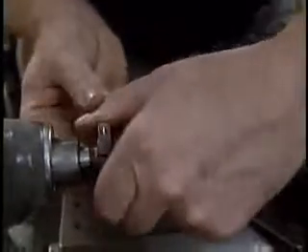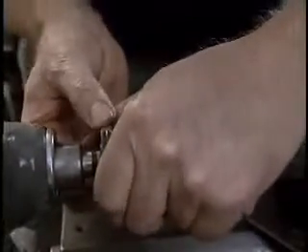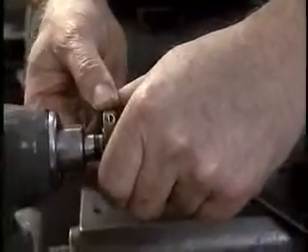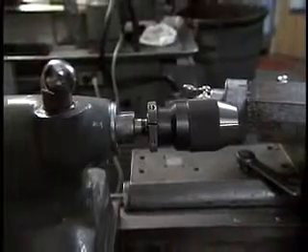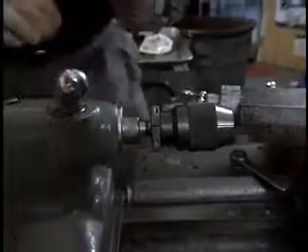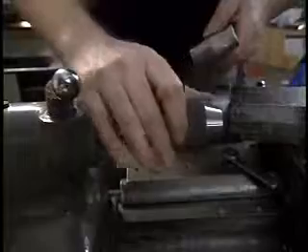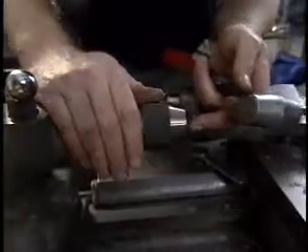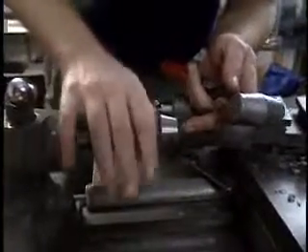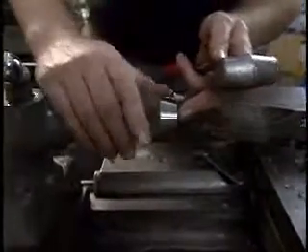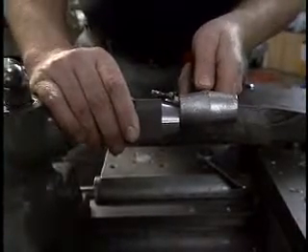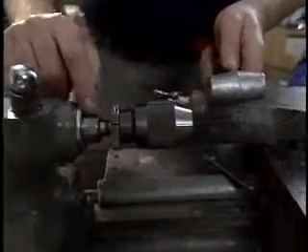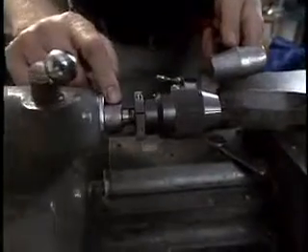We rotate this until the tang fits in place, push it down until it seats, and then with a soft hammer, with the jaws of the chuck that are normally extended drawn back inside the body of the chuck, very lightly tap the chuck to seat the taper into the tailstock.